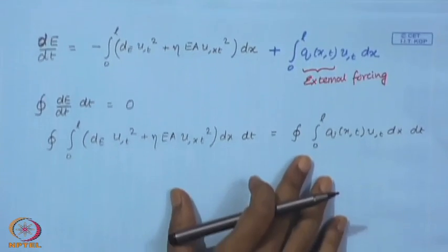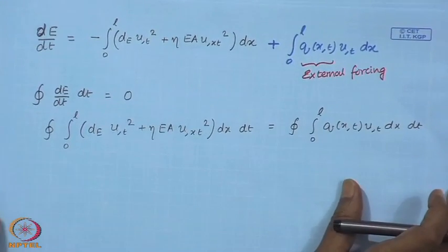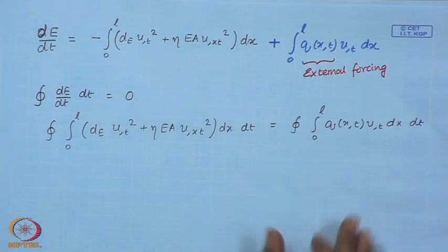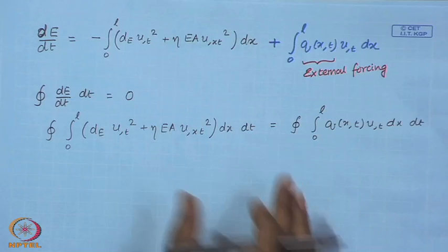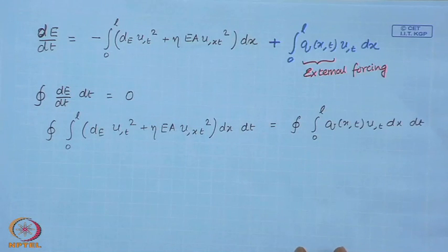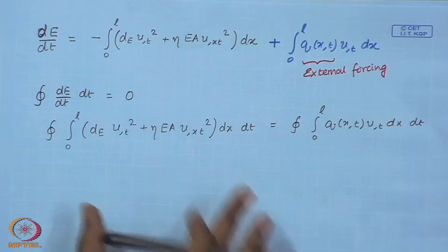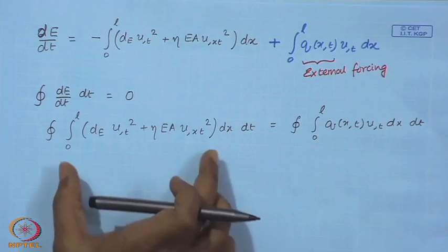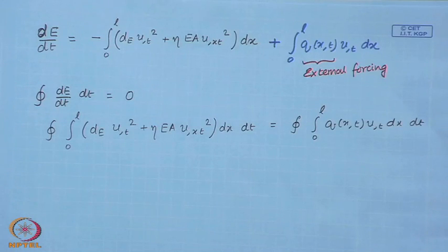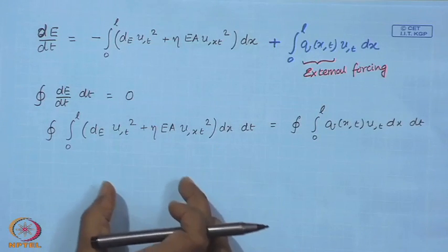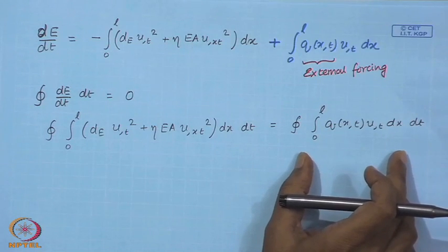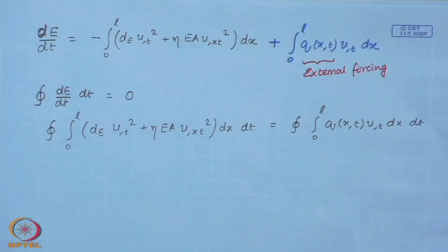What we have concluded is that any initial condition or any initial disturbance must die out because of these damping terms, and what remains is the steady state solution, and that can be used to estimate the energy that is dissipated, and that can be used to model the internal dissipation, as well as you can estimate the amplitude of motion in certain cases.